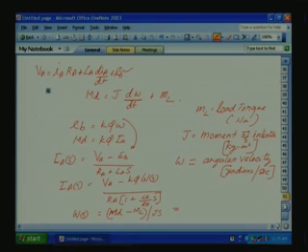Here we can bring this K phi IA, so this will be K phi into IA(s) minus our load torque divided by J into S. S is our Laplace. Okay. Now based on these equations, let us see whether we can write down the input output transfer function or the block diagram of our DC motor. So let us go to the next page.